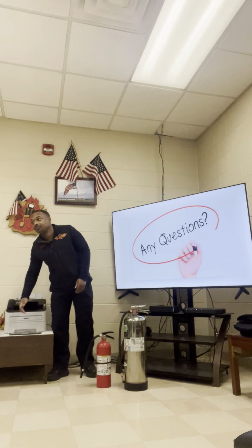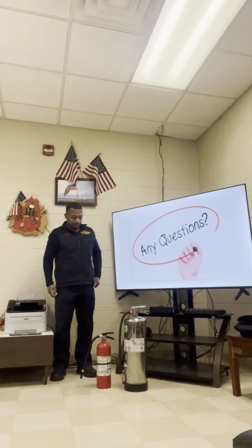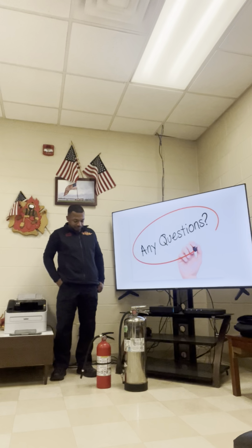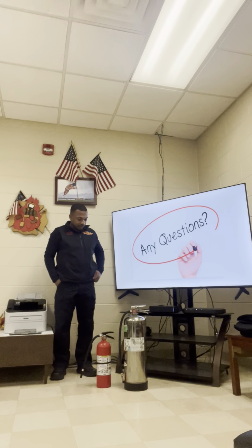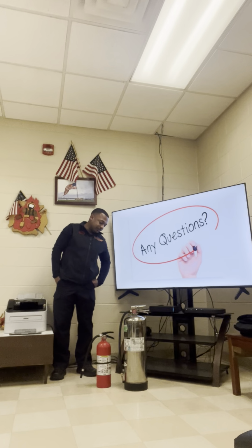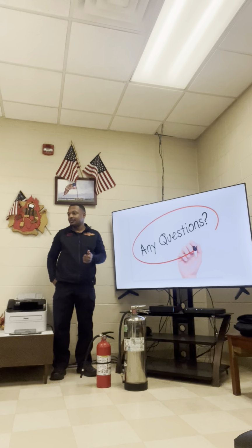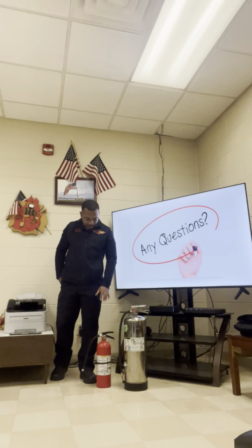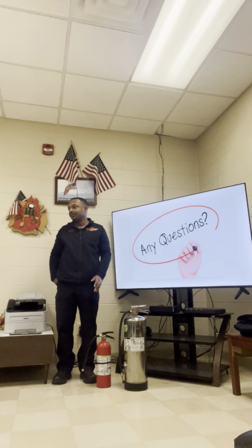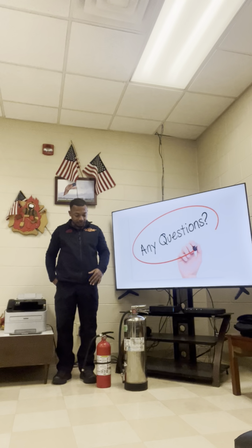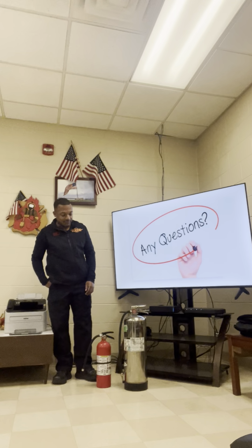What's the life expectancy? How long are they good for? The extinguishers, frequently when they're inspected, they should be good as long as they've been getting tested on time. As long as when they come around, there's no holes or nothing in it. It's holding its PSI. There's no leaks. They get tested every year. If it doesn't pass the test, then it's taken out of service. There is no set time for it. It's basically when they get tested, it needs to be taken out.